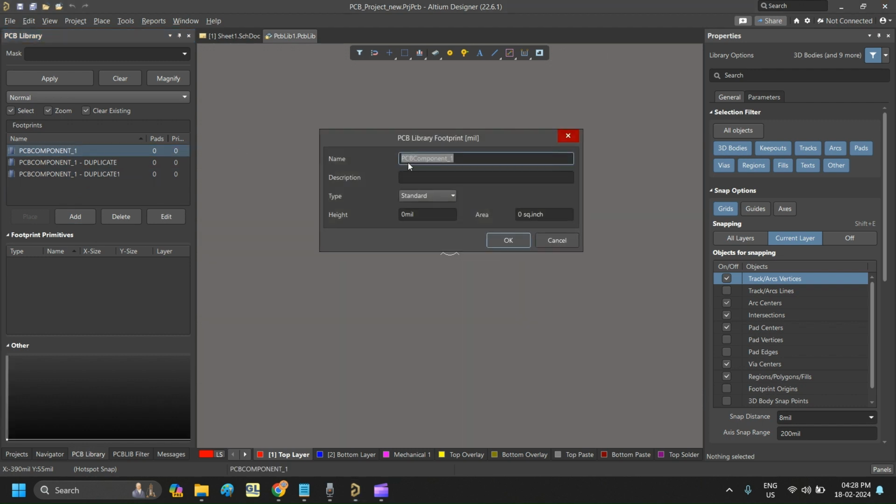Okay, the first one will be our resistor. So I am going to create a 0603 package resistor, and the description also says 0603 with 0.1 watt power dissipation. Like this you can add descriptions; some generic standard description formats are available. Some designers use the format from DigiKey or Mouser, something like that.